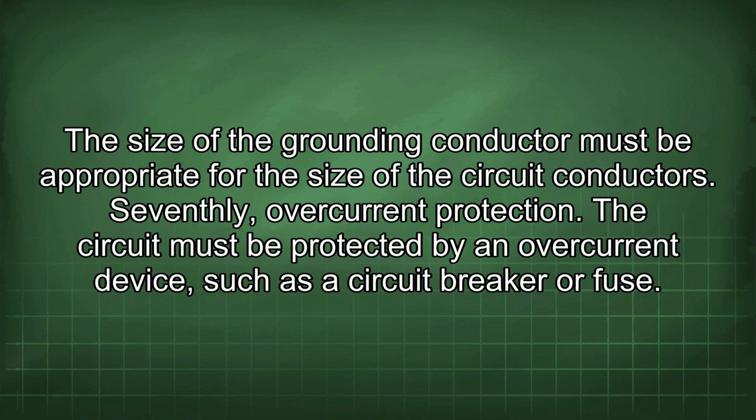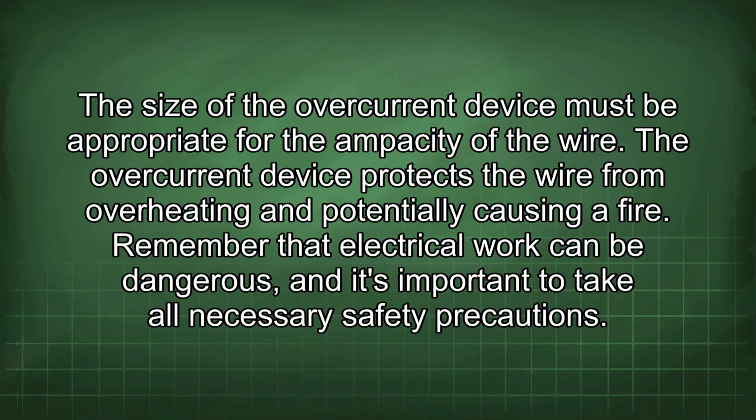Seventhly, overcurrent protection. The circuit must be protected by an overcurrent device, such as a circuit breaker or fuse. The size of the overcurrent device must be appropriate for the ampacity of the wire. The overcurrent device protects the wire from overheating and potentially causing a fire.